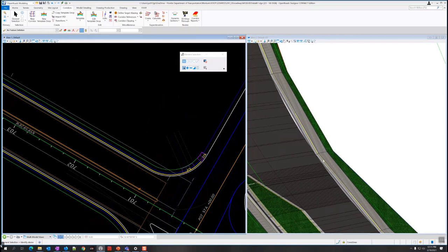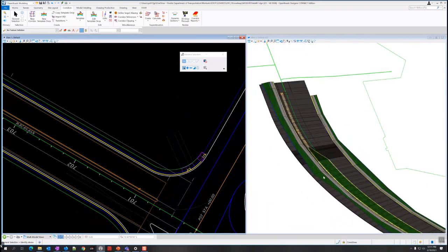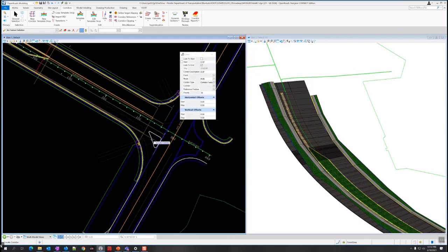Let's go ahead and add the point control for the other side. That's step number 8. It says basically repeat steps for the left side. So again, we go to point controls right here, this edit menu. The second time I don't have to click the drop-down, because notice this changes, since that's the last command I used on this split button. So I'm just going to click the button now, create point control, and it asks me to locate the corridors.